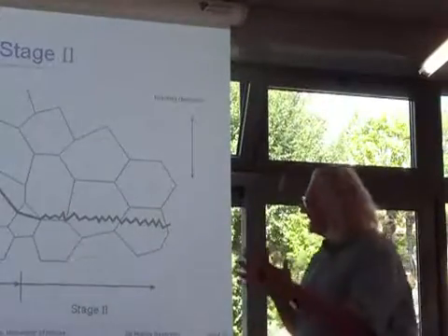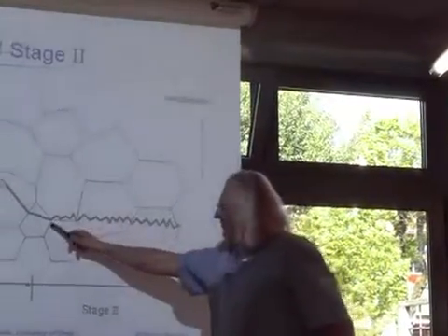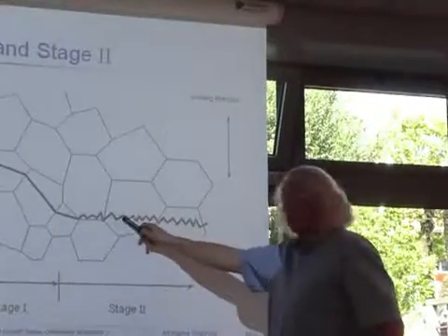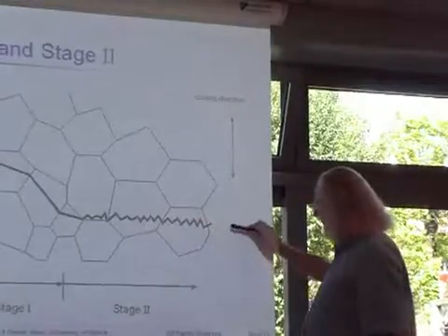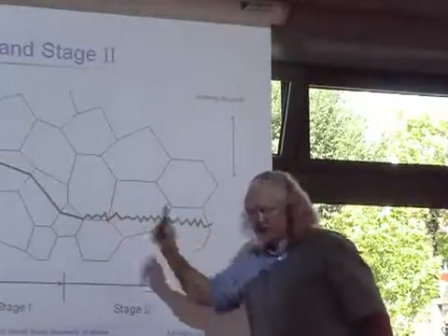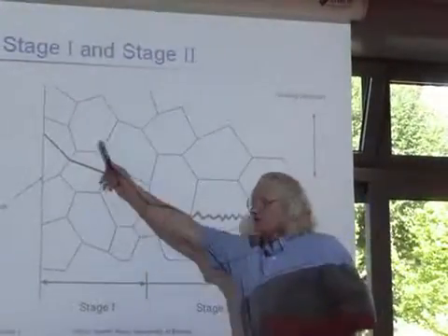If I look very closely with a microscope, they grow back and forth in shear, because again, all plastic deformation is caused by shear. But macroscopically, they grow in tension. And this is a big problem now in fatigue. What stress system do I want? Do I want this one, things driven by the shear stress?